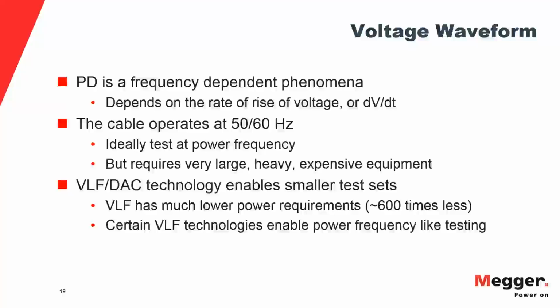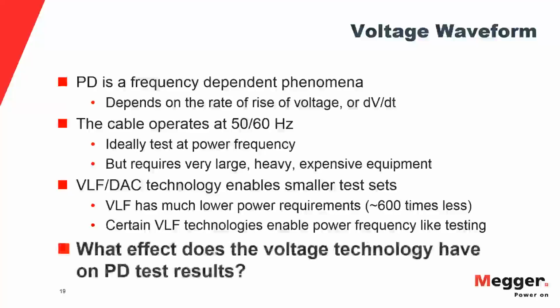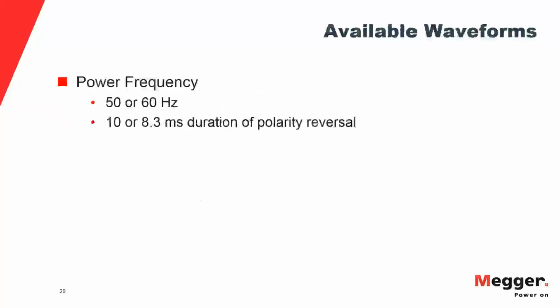So that's the brief introduction. I'll talk about the voltage waveforms that we have available to us. It's important to keep in mind that partial discharge is a frequency-dependent phenomenon. It depends on the rate of rise of voltage, or the dV/dt, especially at the point of zero crossing.